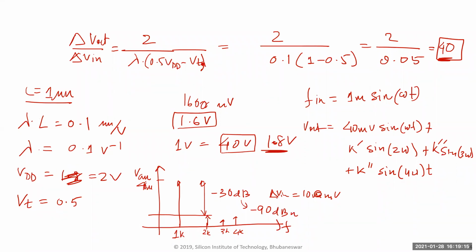This is basically in the audio world, you hear a jarring sound, like at functions or the marriage processions, that's like a lot of F2s, second harmonics, basically. That's what it is, right? If you're hearing a sweet sound, there's no second harmonic. So if you want a sweet sound, then it's minus 120, 140 dBc. Then your delta V needs to be really, really small, like 1 billionth.